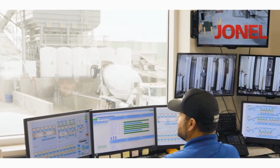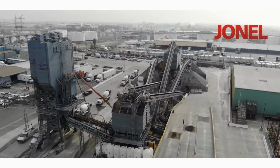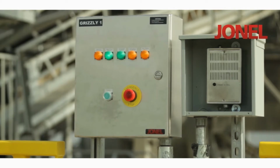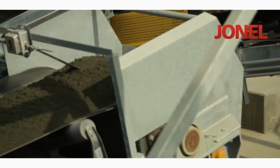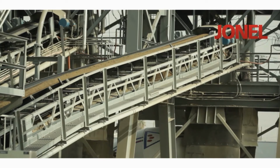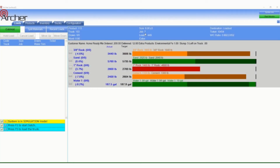In today's lesson, we will discuss how to set up and configure charging sequences. A charging sequence prescribes how and in what order materials will charge a truck or mixer. You may also refer to it as a discharging sequence, since it only affects measured materials and their discharge link elements. Charging sequences apply only to automated loads and do not prevent you from manually discharging materials in an alternate order.